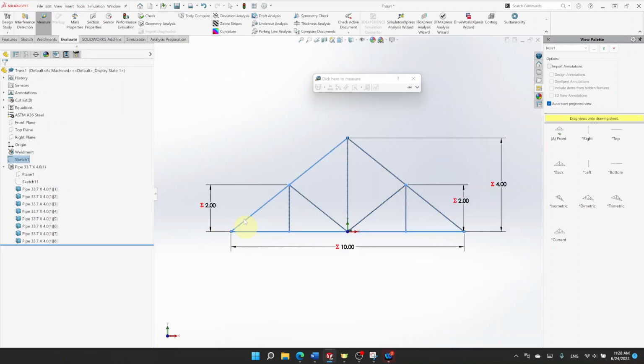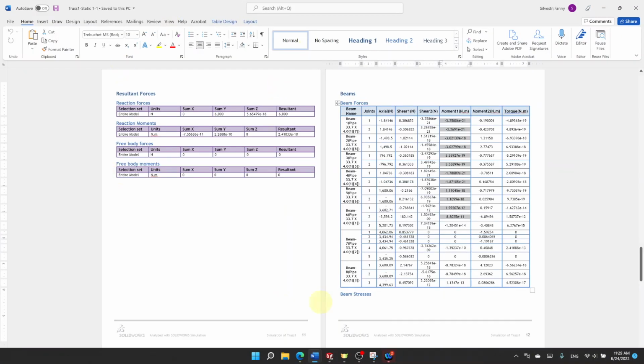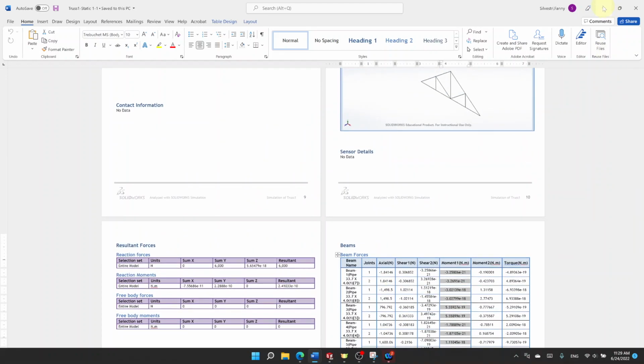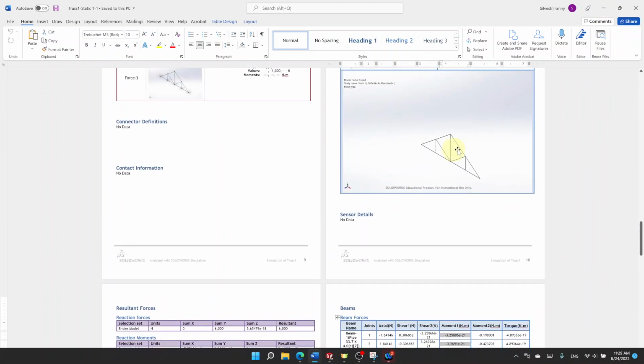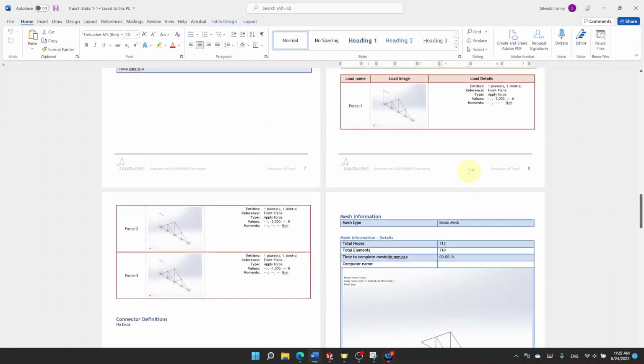Hope you like it. When you save your truss and everything, you will have the statics analysis that is saved. That will create a lot of documents in the folder. You will also have your report saved in the same folder where you work. And you can edit this document to add more information if you want. Before you start the analysis, make sure your truss is centered and zoomed enough, so after that it takes more space on each picture.